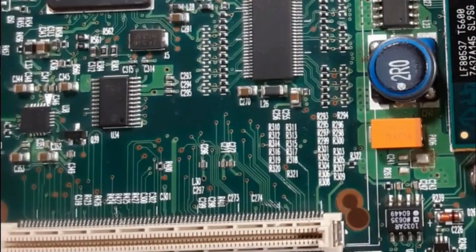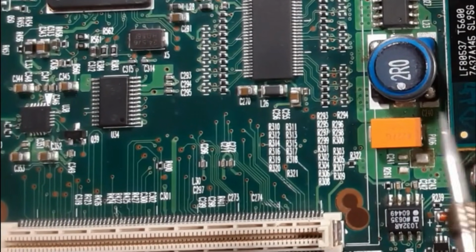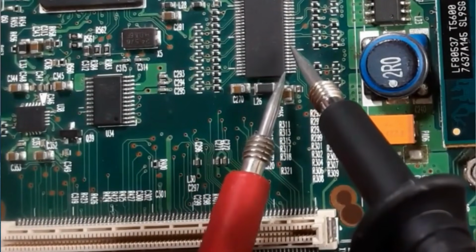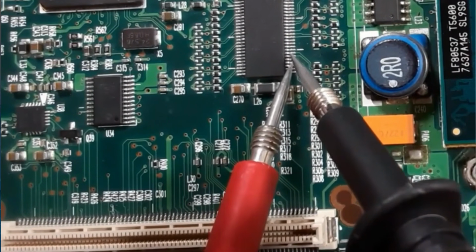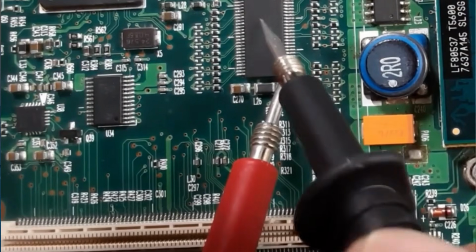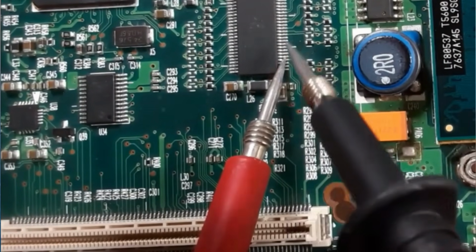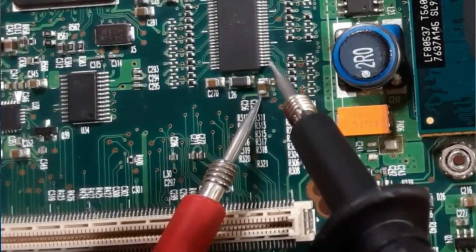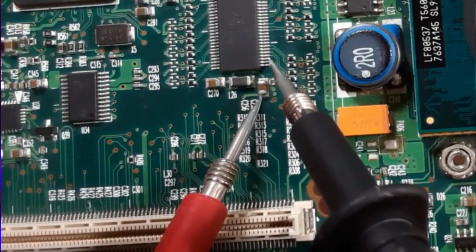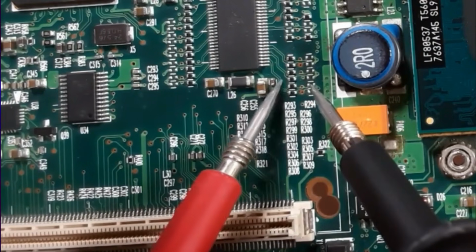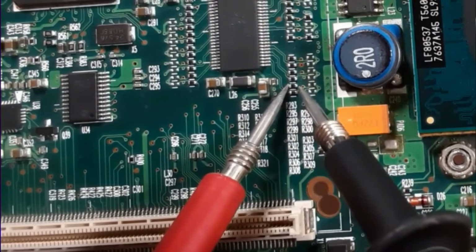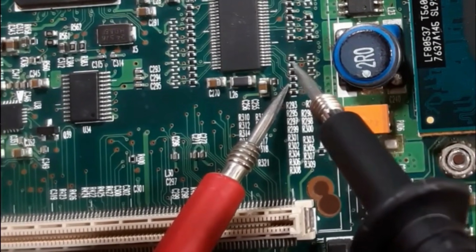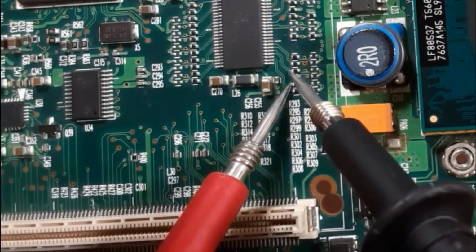Okay? And you can use a technique here. If you want, for example, to test between two pins here, avoid taking the test or measurement here, because you can damage this IC if you short it here. You can look for the extension of this pin. For example, for this pin, its extension is this resistor. So I will put one probe here, on the extension of this pin, which is this resistor, and I will put the other one here. Okay?